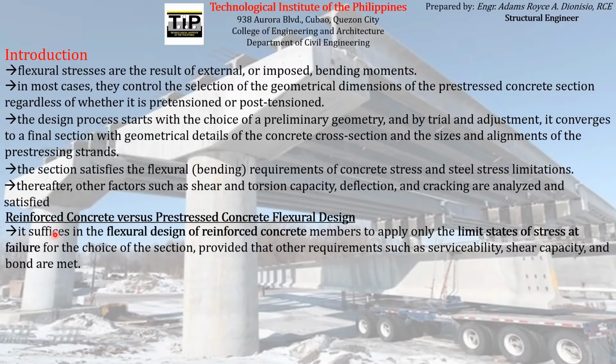It suffices in the flexural design of prestressed concrete members to apply only the limit states of stress at failure for the choice of the section, provided that other requirements such as serviceability, shear capacity, and bond are met. This comparison is actually limited to the flexural design of both reinforced concrete and prestressed concrete.